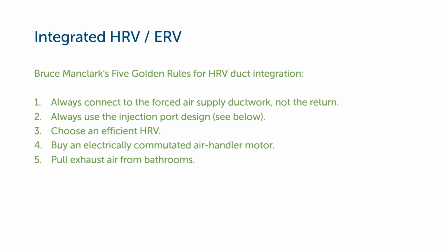And Bruce Manclark hit it right on the head with his 5 golden rules for HRV duct integration. Number 1, always connect to the forced air supply ductwork, not the return. And the way to do that is number 2, always use the injection port design. I'm going to show you that in the next slide.